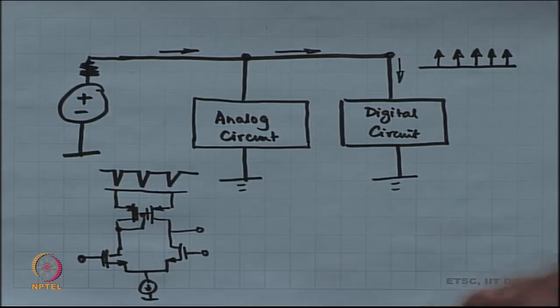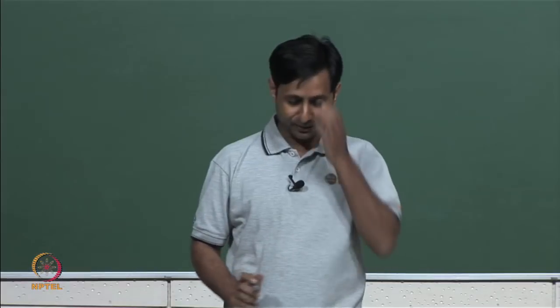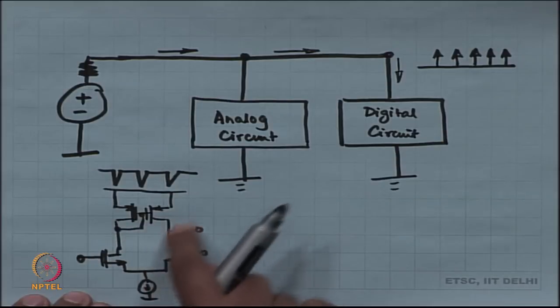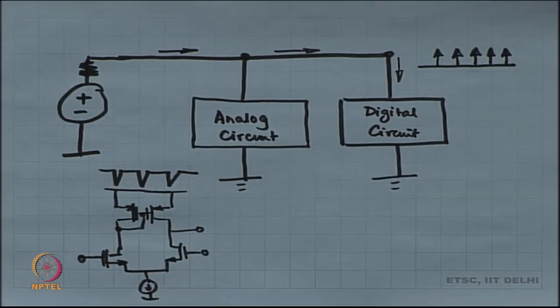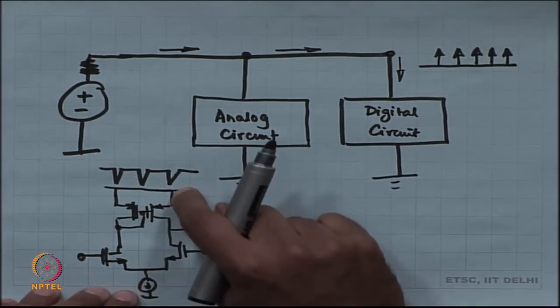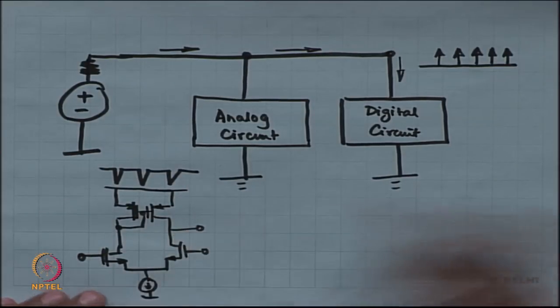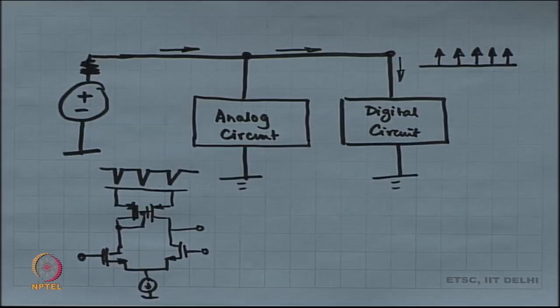That is going to get amplified in terms of voltage in some other analog circuit, some differential amplifier you have got. The power supply is going up and down, and therefore, that will get amplified. Okay. So, in general this is all very bad news. You do not want this power supply voltage to move at all.